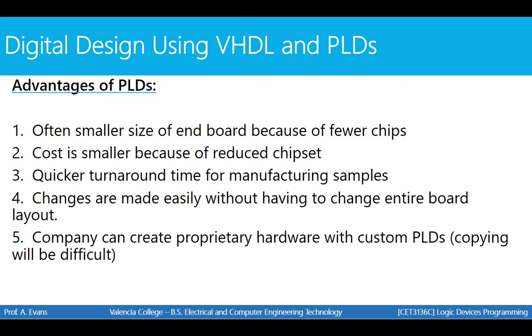Imagine trying to wire a particular circuit using the ICs you used in Digital 2 and then changing the function of that circuit slightly, but that might cause a massive amount of rewiring. With a PLD, a small change in logic could be a very small change in code, and then you can just reprogram your PLD with that upgraded circuit. So changes are easily made without having to change the entire board layout of a particular circuit. And then with PLDs, a company can create proprietary hardware with custom PLDs for a specific function.